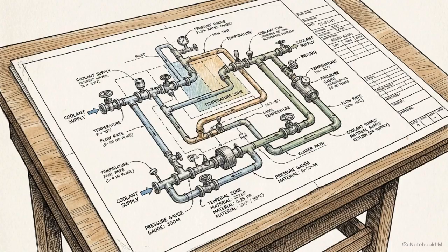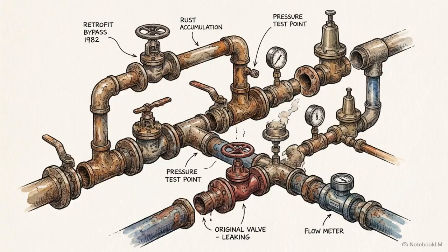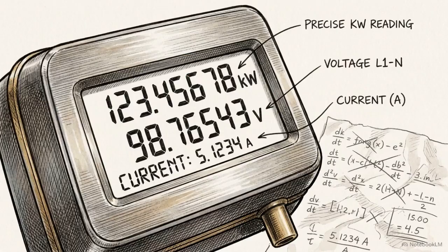Avoid trusting design blueprints exclusively. Aging systems and retrofitted equipment rarely operate at their original design specifications. Calculating is better than estimating, but measuring is better than calculating.